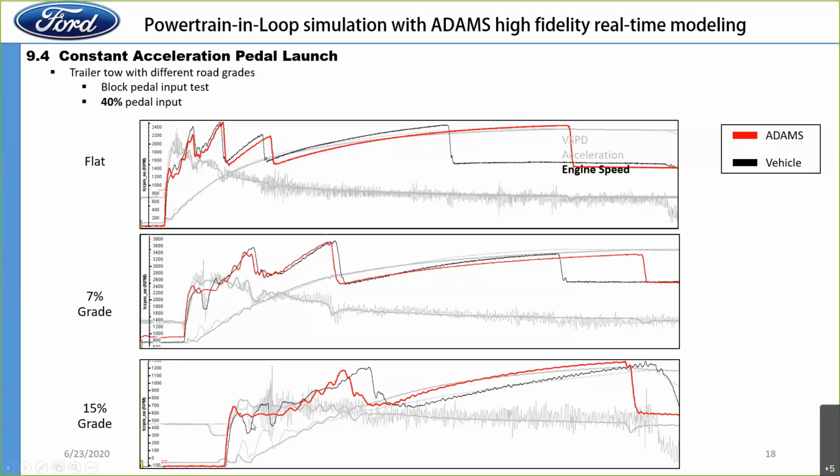What I believe, you see there's a gap between the real vehicle and our testing of the engine in the cell. I believe there's tire slip, a lot of slip right now, and in the model we don't have such a significant slip.